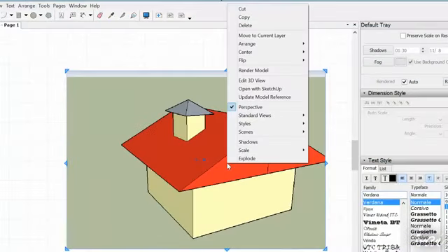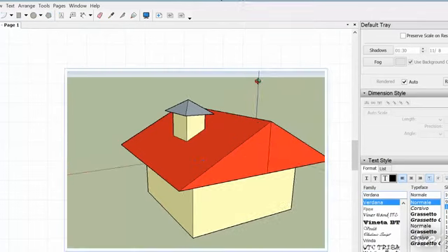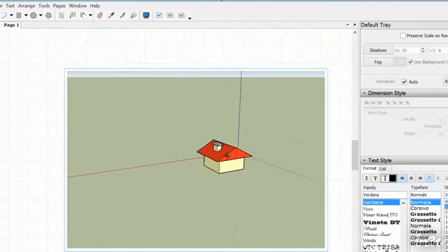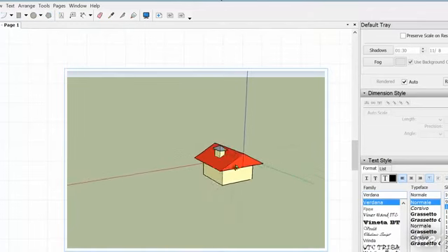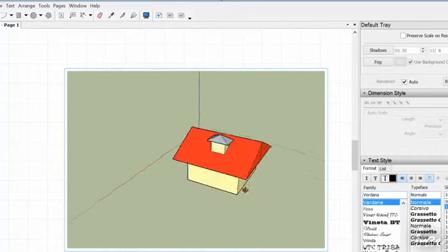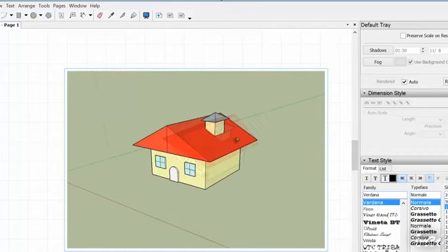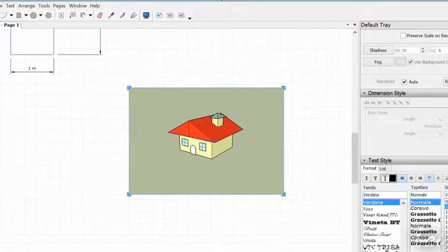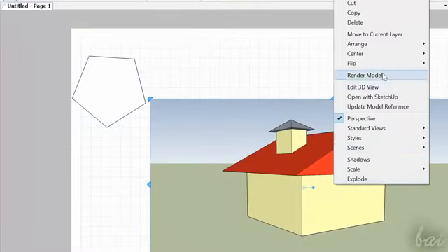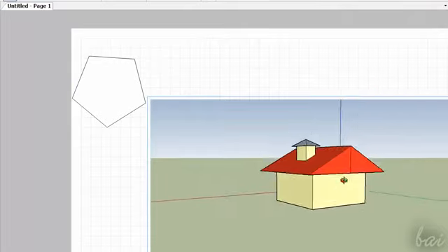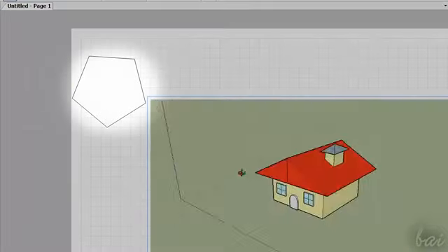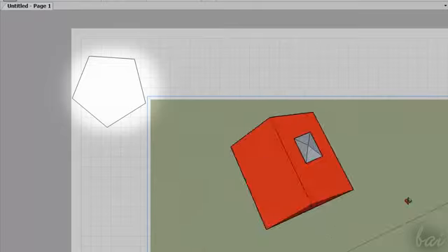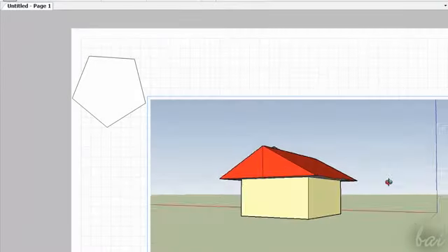You can still change point of view. Just right-click on the project and go to Edit 3D View to use the Orbit tool inside. When you finish, click elsewhere. Keep in mind that the orbit affects just the objects inside your project, not anything added or created through LayOut.